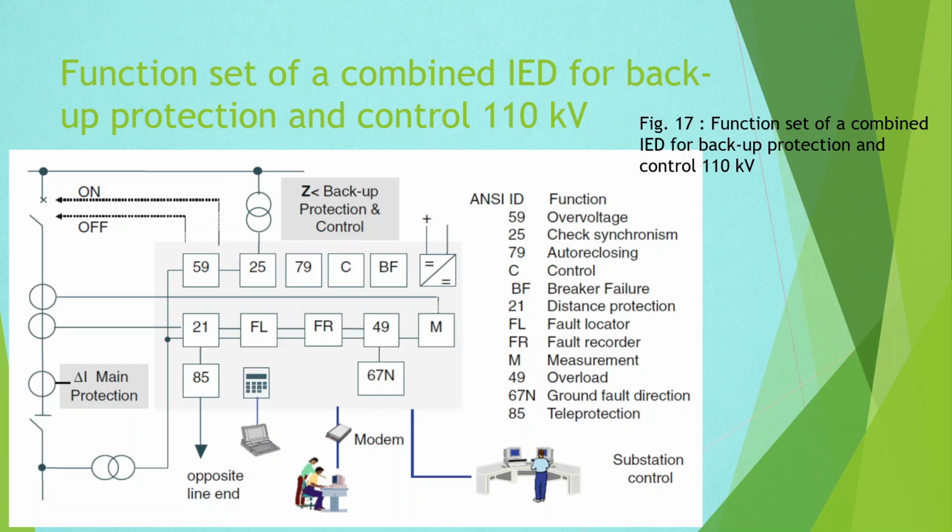In these networks, the shorting of one phase to ground does not generate high currents. In this figure, the benefits of the communication interface of the IED are also demonstrated. Here, IED communication interfaces are used for teleprotection, for external reading of protection data or parameter setting, and for the link to the substation control place.